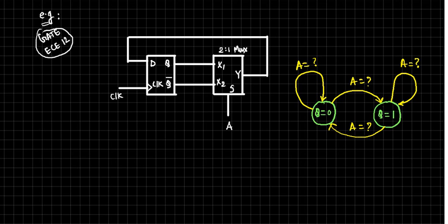So, see here. What I asked was, I wouldn't have drawn this diagram, but just to give a soft start, I have drawn it. Otherwise, you have to go for your own diagram. What is this? This is the state of this flip flop, right? The D flip flop. What does it do? It will simply transfer. It's a transparent latch. So when the positive edge of the clock arrives, it will simply transfer data from D to Q, isn't it?